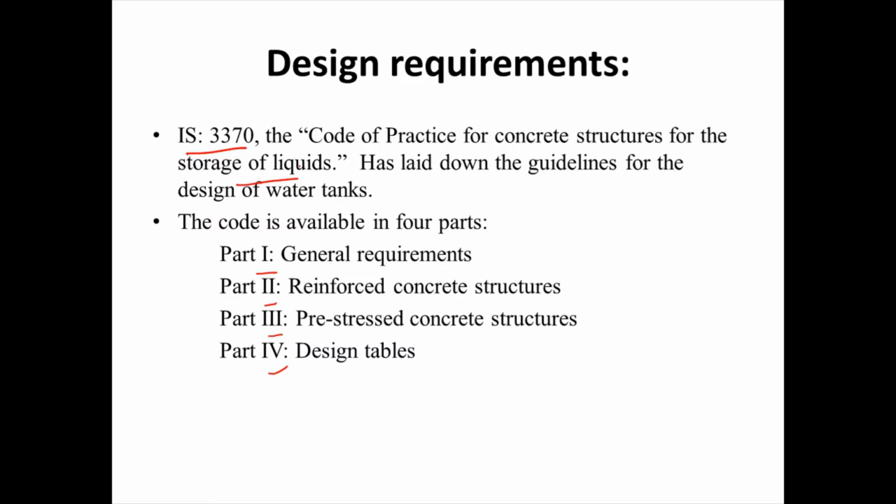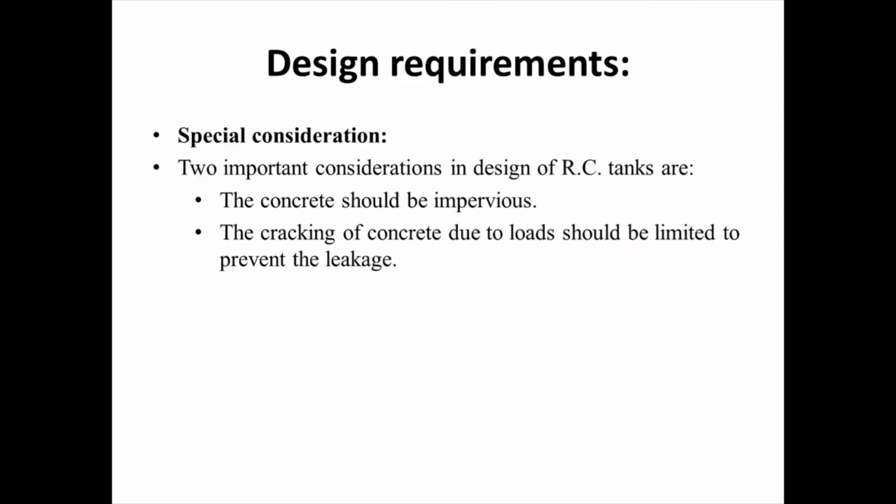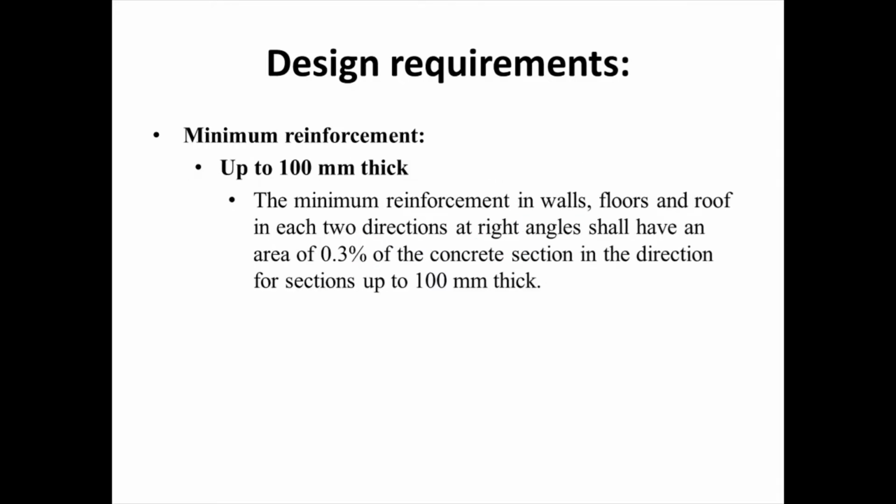Okay, special consideration. For the design of a water tank we have two considerations here. First, the concrete should be impervious, meaning no leakage, and second, no cracking in the concrete due to loads. Impervious means your water will not flow out through the concrete. So these are the two considerations. And now we have the minimum reinforcement.